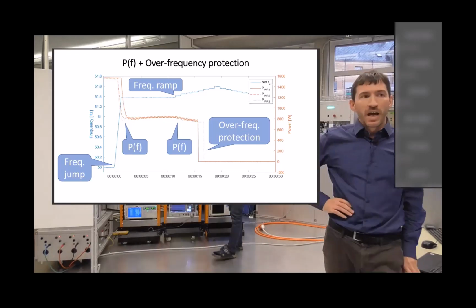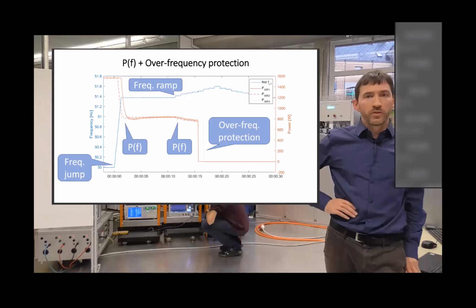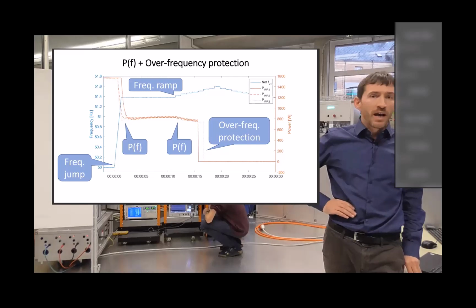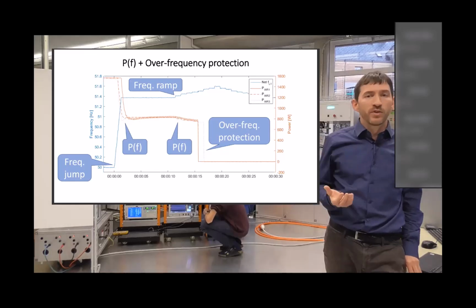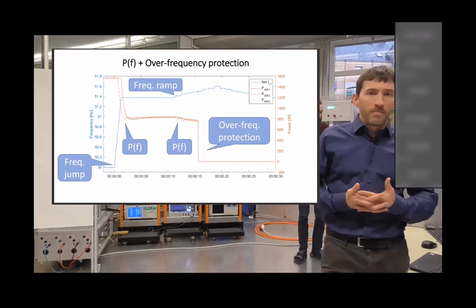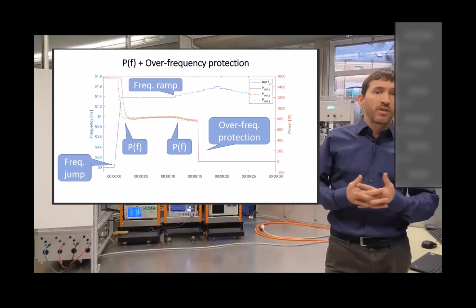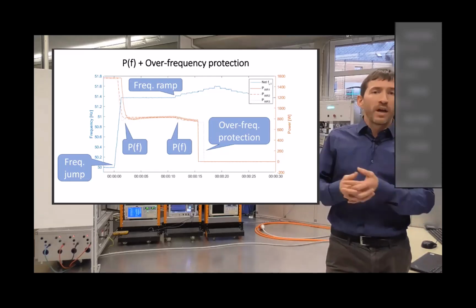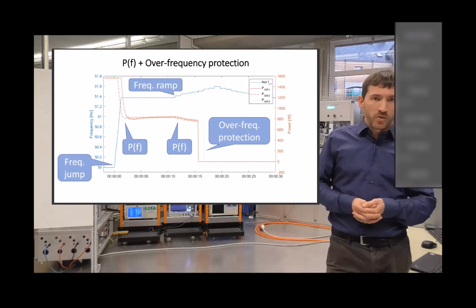And you can see how all three inverters, that's the measurements of all three inverters together, they all have reacted correctly. They all went to the same power level, but you see that the speed, how they reacted, when exactly they reacted, that differs a bit. And it's the challenge now in our testing code to evaluate this behavior and to say what is good enough, what is not good enough, because of course the standard itself, the grid code, wouldn't tell us how exactly it should behave. It would just tell us where and about in what speed this behavior should be shown.